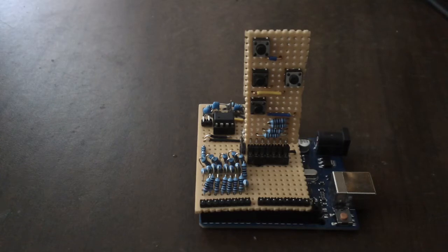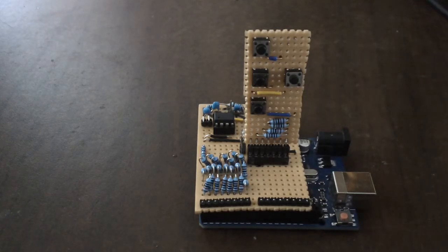If you get a bandolier of resistors, because they're all manufactured at the same time, you usually find that they're very, very close. You need to be better than 1%. And I measured each and every one of them. There were a few that were a bit outside, so I threw those away. Well, I didn't. They just went into my junk box so I could use them for something else. But that got that lot made up.